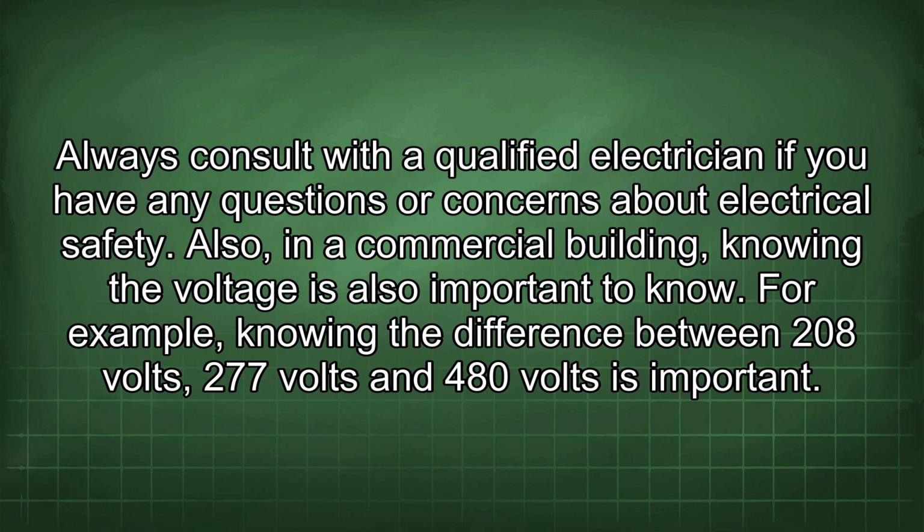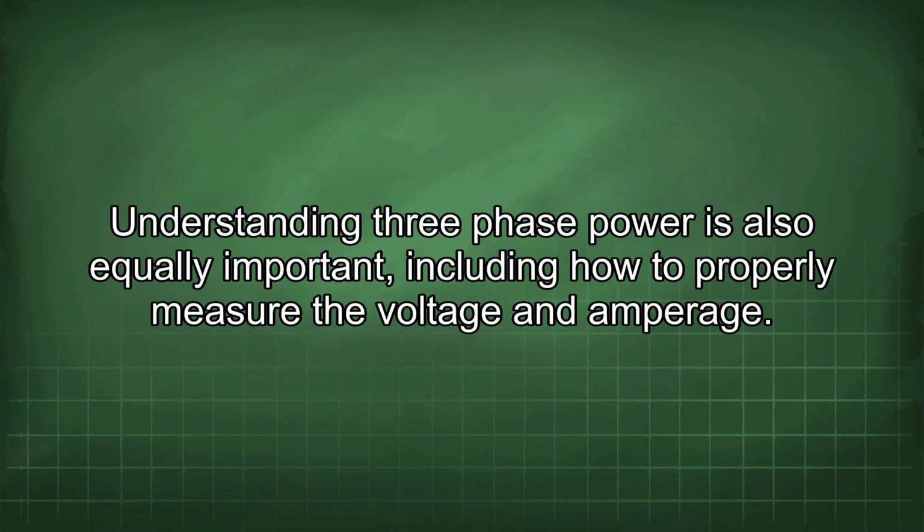Also, in a commercial building, knowing the voltage is important. For example, knowing the difference between 208 volts, 277 volts, and 480 volts is important. Understanding three-phase power is also equally important, including how to properly measure the voltage and amperage.